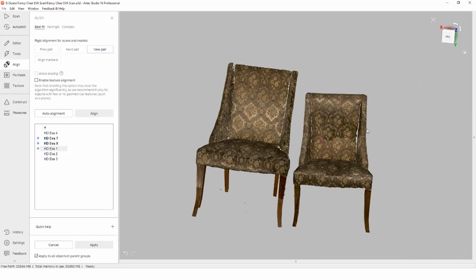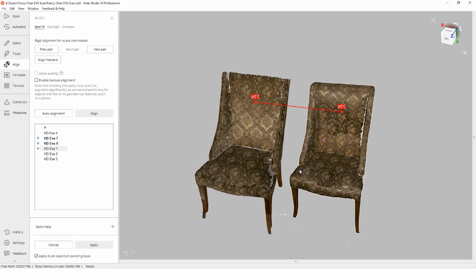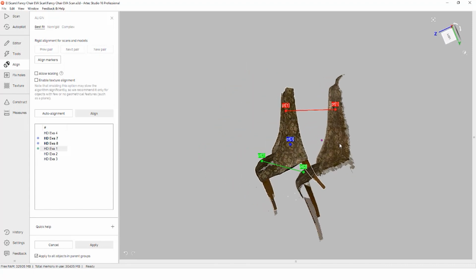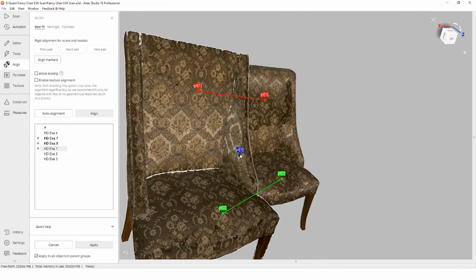To help with rotation, we can double left click our scans in the workspace, which can change the center of rotation, indicated by a pink dot. When we're ready, we can start left-clicking once on an unregistered scan, and then selecting a similar area on the registered one. We don't need to be perfect with this, just the same general area works.